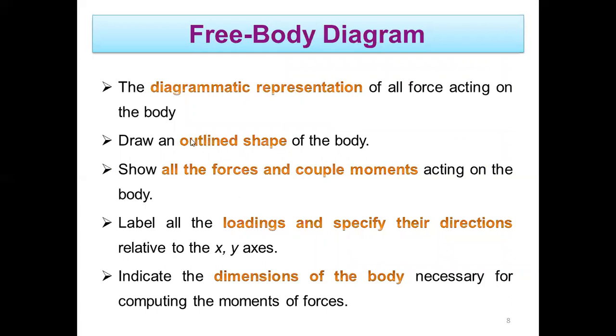First we have to draw the outline shape of the body. Then represent or show all the forces and couple moments which are acting on the body. Third, label all the loadings and specify their direction relative to the x and y axes. Indicate the dimensions of the body necessary for computing the moment of forces.